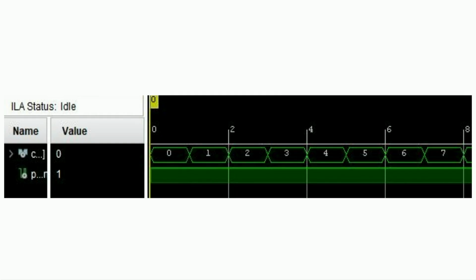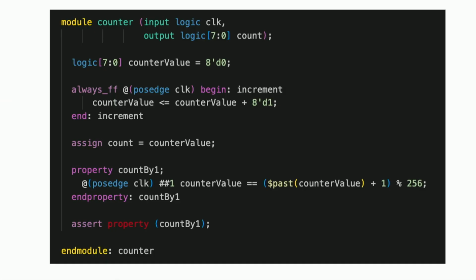So we have a path from algorithmic C-style descriptions as many concurrent processes which orchestrate and communicate with each other, and they get turned into a circuit graph by some tooling through a process of synthesis. This, in general, can be quite complicated. It could take many, many hours to synthesize a circuit netlist from these algorithmic descriptions.